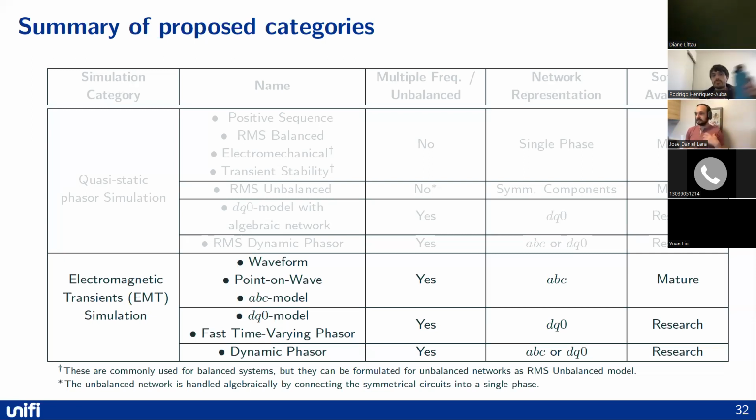But the challenge of these types of simulations is that they also generate a lot of low quality information. Sometimes the dynamics of the system don't require sampling at all of the 60 hertz or at 600 hertz and so on. You don't need all the detailed ABC signals to obtain information about the dynamics of the system.